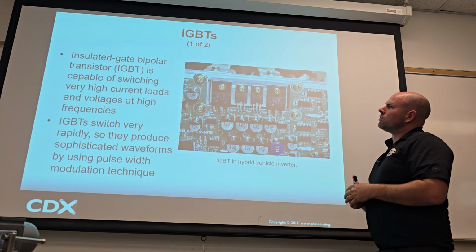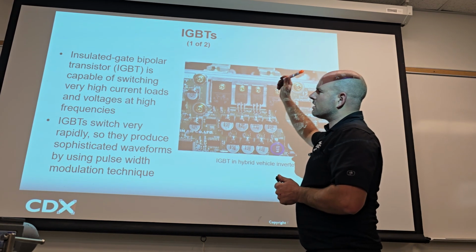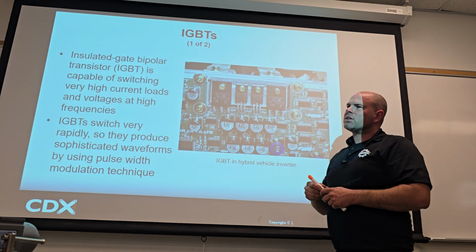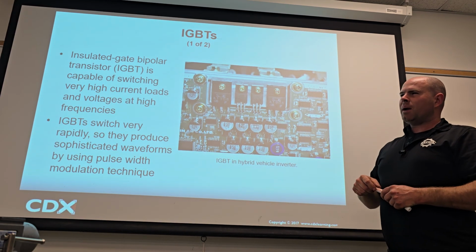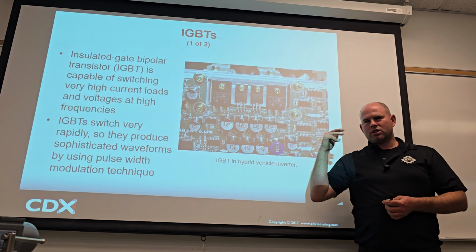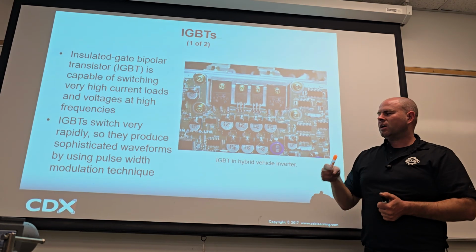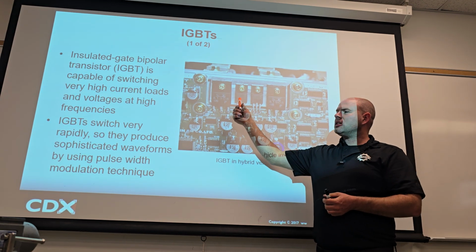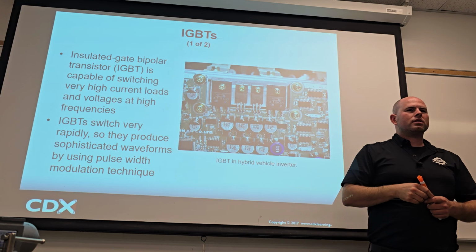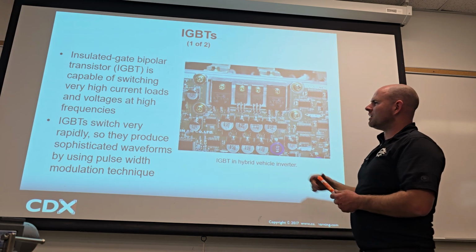So it's good to know, especially IGBTs. A lot of times you'll see this introduced when you get into the hybrid stuff, because in a hybrid, we're going to take the DC and we're going to basically artificially create an AC sine wave, and we're going to do that through these IGBTs, and they're going to be really high current to be able to run those AC motors. Cool. So it's kind of similar.